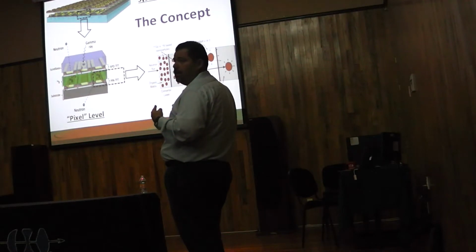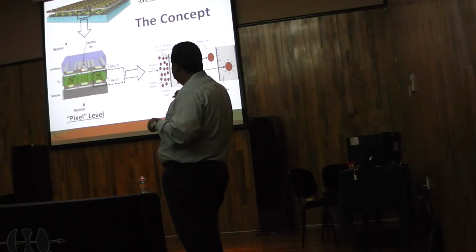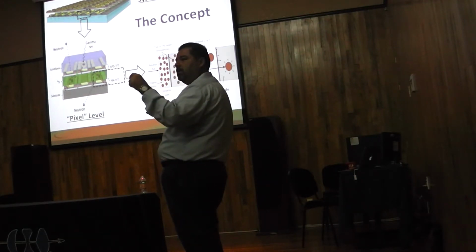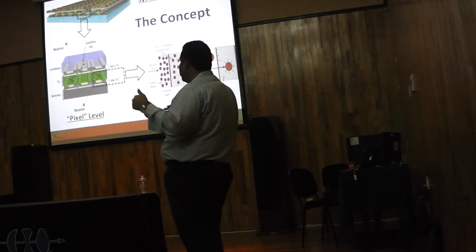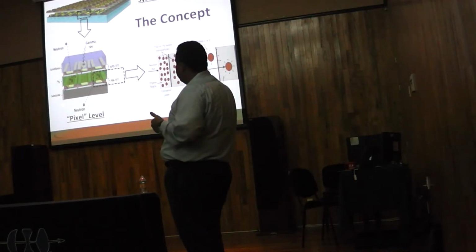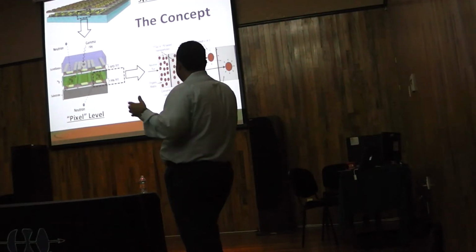If I'm looking at gamma detection, I need to have a scintillator, so the gamma will interact with the scintillator. It will generate a photon as a consequence of that interaction. That photon will interact with my avalanche photodiode, which will generate one electron and hole, which will be accelerated with the electric field, and will go through the avalanche process, and I can detect the gammas now. So this is the concept, right? I showed you that we can fabricate the PIN diode, we can fabricate the avalanche photodiodes. We can simply use commercial plastic scintillators to do this kind of system.